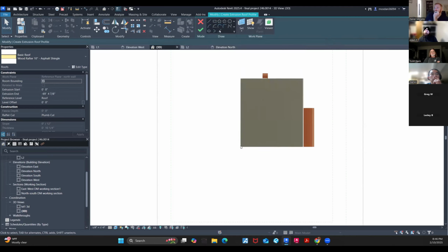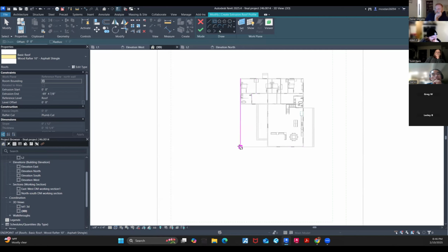So if you click that square button, the rectangle tool, you can click that bottom corner. There you go. Yep, click that one, then click your bottom corner. Now, one thing right now, you can't really see anything, so go ahead and go down to the bottom of your screen. Have you clicked? No, perfect. Don't click, don't click. Okay, go over to the blue cube and let's put this in wireframe. Okay, so now we can see underneath it what we want to cut out.